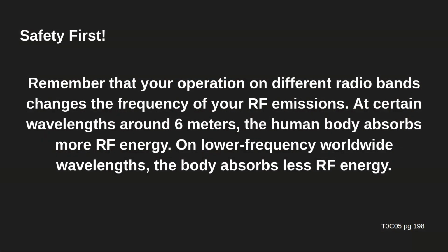Now remember that your operation on different radio bands changes the frequency of your RF emissions. At certain wavelengths, around 6 meters, the human body absorbs more RF energy. On lower frequency worldwide wavelengths, the body absorbs less RF energy. And that's also a question.